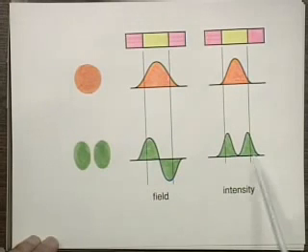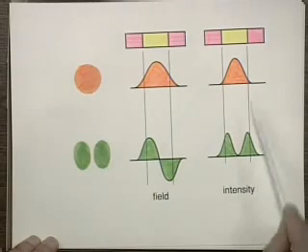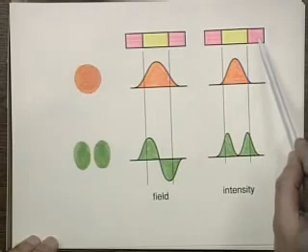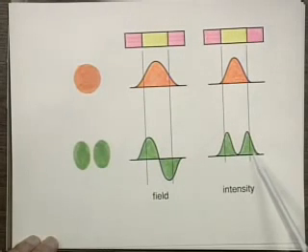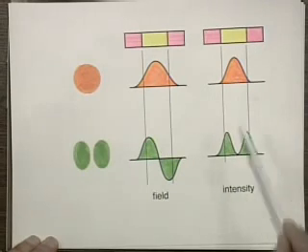And what you see here is that the size of this higher order mode is bigger than the lowest order mode, and more of it will propagate in the cladding than in the core. So in terms of propagation constant, or how fast they propagate, this one propagates more in the cladding than this one, and since the index is smaller in the cladding than in the core, this one will go faster than this one.